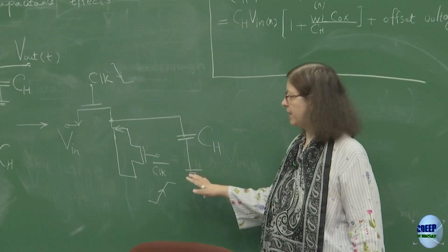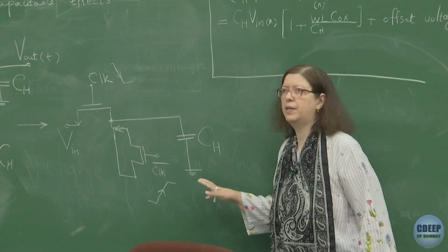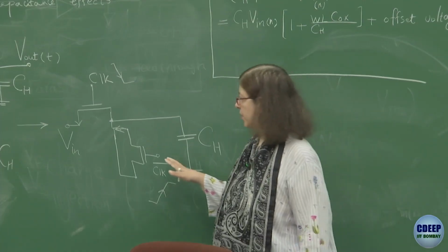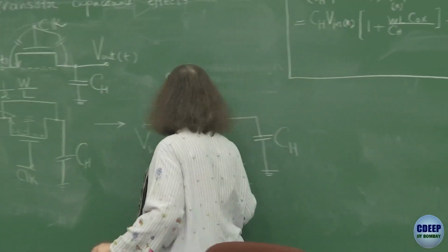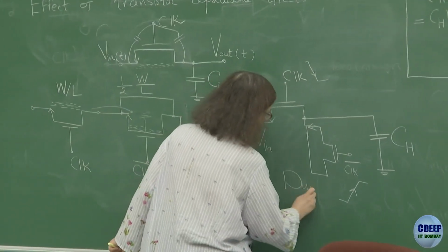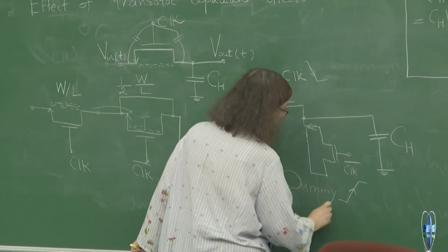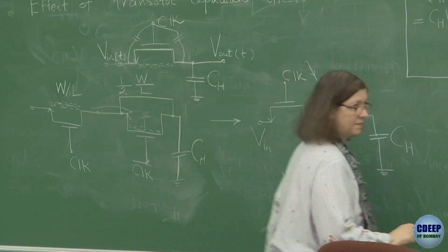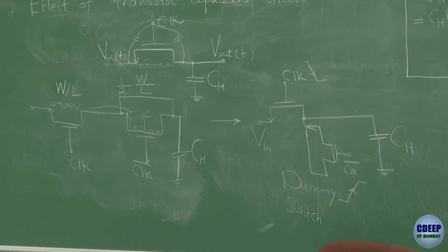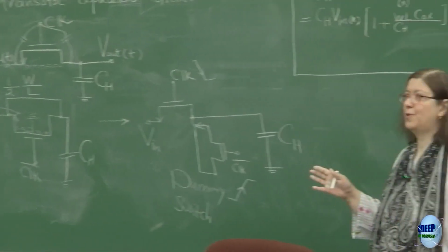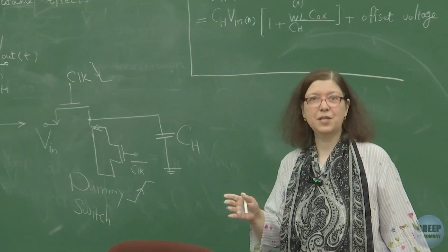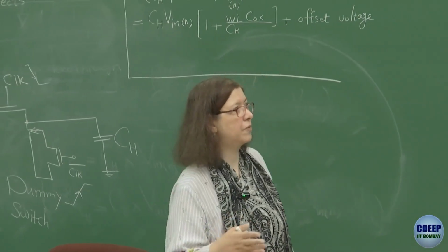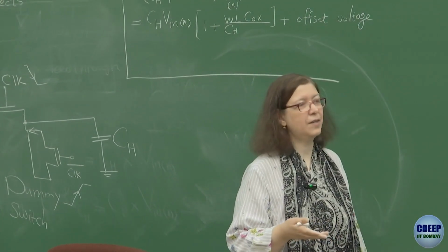Okay, see, dummy switch eventually is a very common technique. However, let me write also dummy switch. However, with proper simulation, and now you can understand how proper simulation matters. Because sometimes you may not see clock feedthrough, still is fine, but you may not see proper charge injection, just because your simulations are not right. Or sometimes you see the problem is not solved because your simulations are not right.